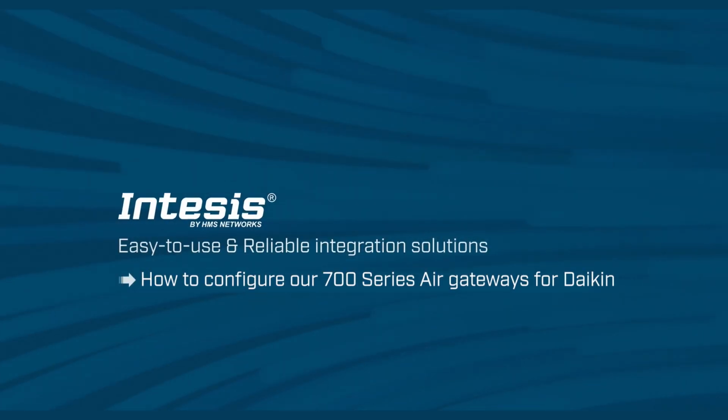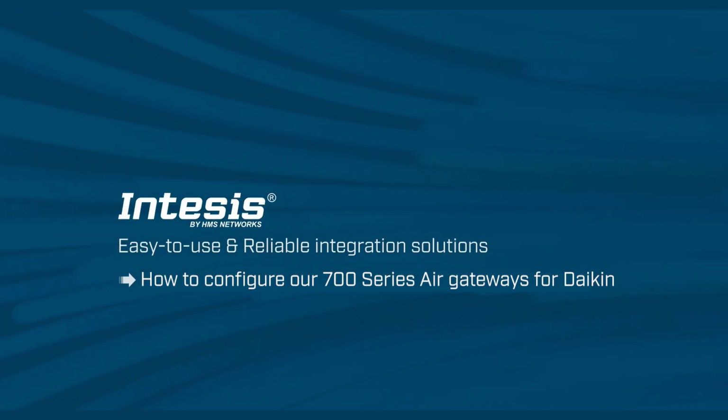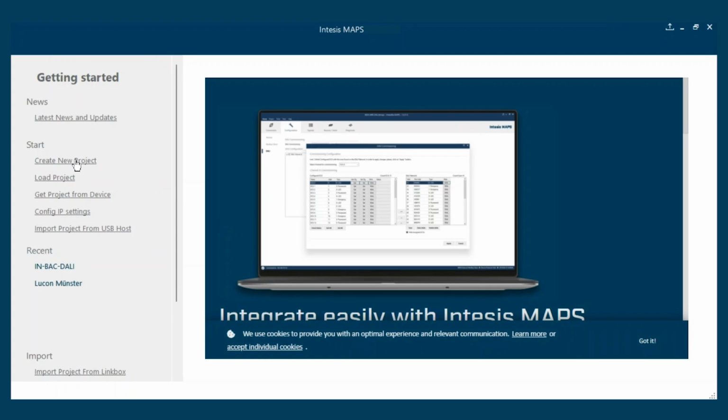Discover how easy it is to configure the Intesis 700 series gateway for Daikin. The Intesis 700 Air series gateways are configured using our software MAPS. Once MAPS is open, select Create New Project from the left menu.